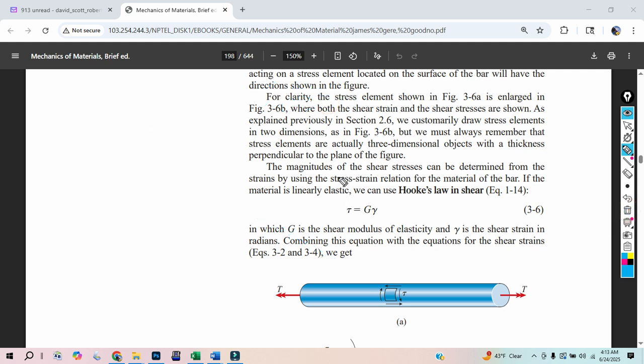And so that is the whole idea of relating Hooke's Law in shear, is that if I see an angle form and I can measure it, and I know that angle can be anywhere from 0 to 0.004 for steel, let's say, then if I measure the angle somewhere there, that number is proportional to the stress in that thing.